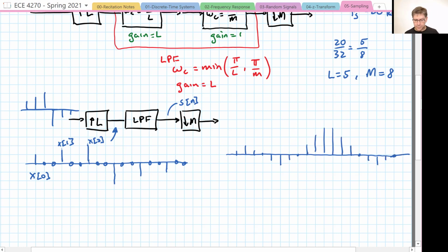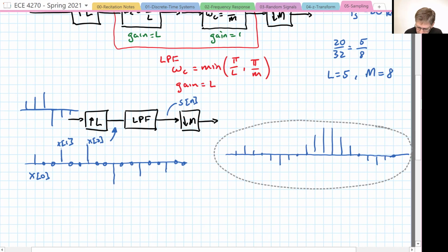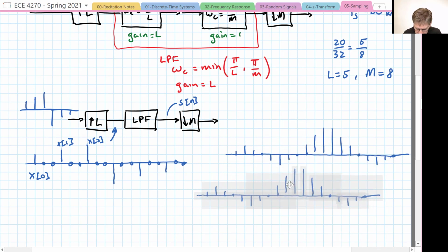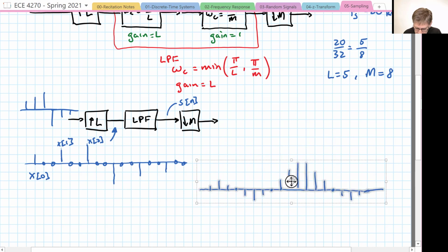And so on. Okay, so we're going to be throwing away most of the samples. So what impact is this going to have on our overall filter operation? First, you can guess that we don't need to calculate every output sample if we're not going to use every output sample. Another thing to consider is that most of the input samples are going to be 0.